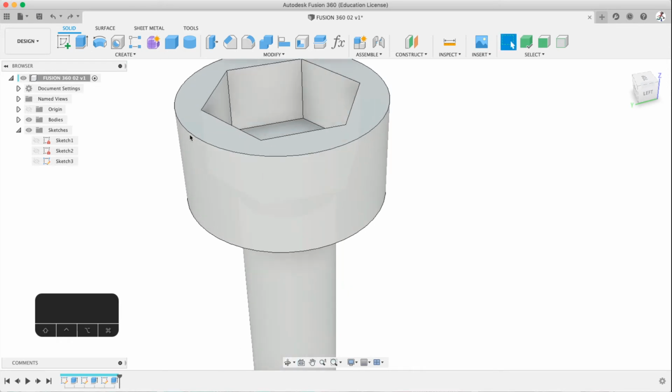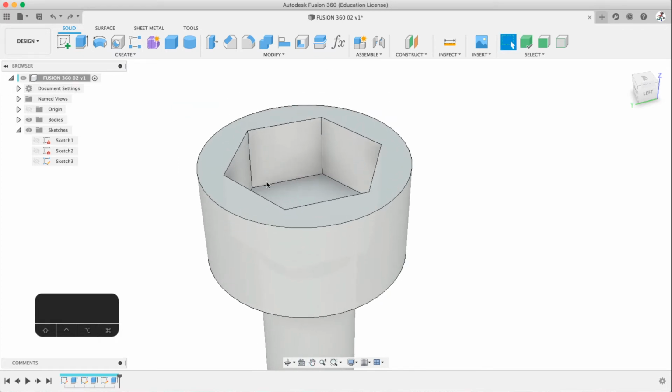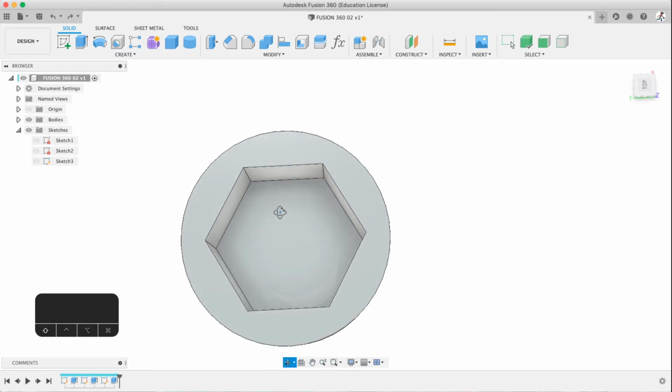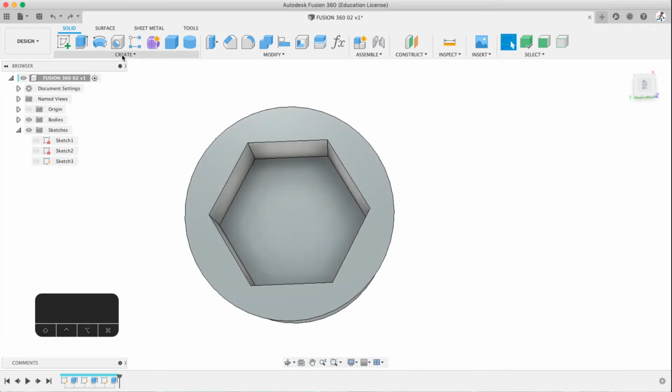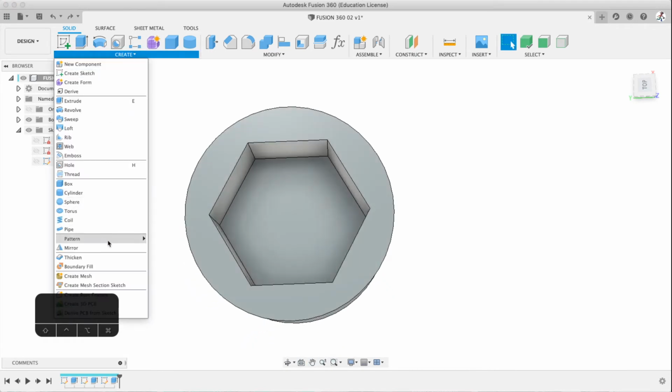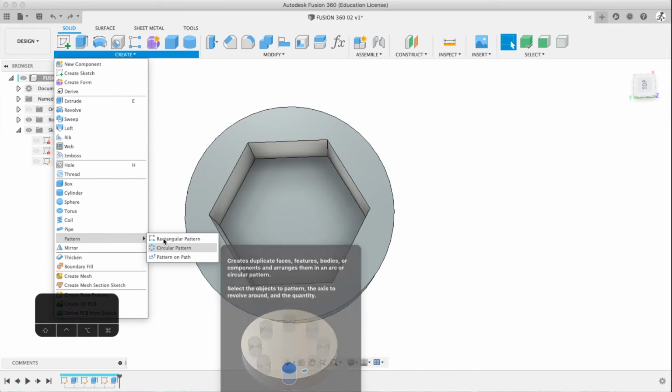Next, what I like to do is actually create these little ridges on the outside. We're going to use a few more tools, and this is where we get a bit more complicated, but it's going to be a tool that you might fall in love with. I do myself. It's a great tool, the circular and even rectangular patterns. This is for repeating objects. You can see that the example shows the main object plus it repeats itself around.